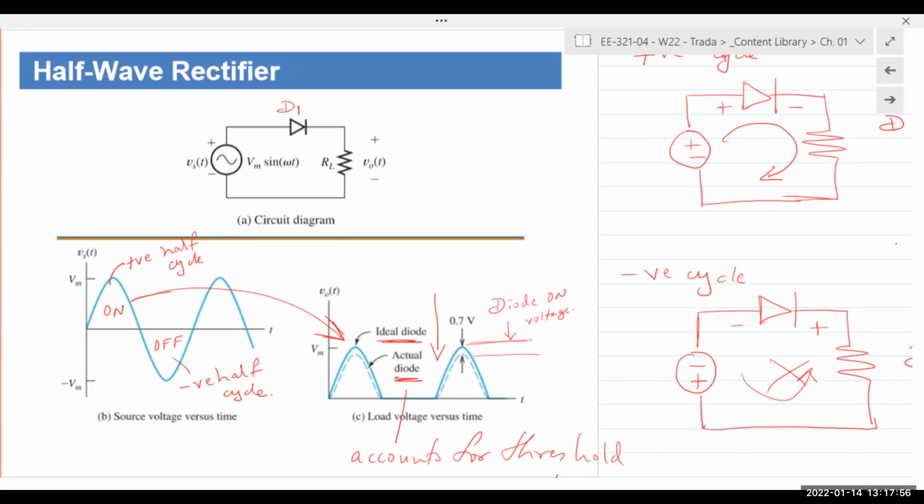It is actually a step-down transformer. You plug it into the wall and it takes the 120 volts AC coming out of the power outlet and steps it down to 12 volts AC. So the output over here is 12 volts AC. It's not rectified. I just wanted to bring it in for a little bit of show and tell.